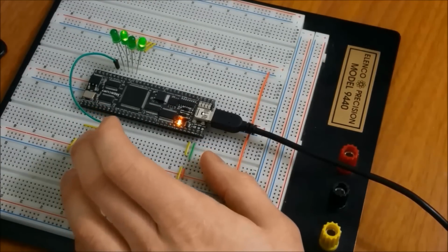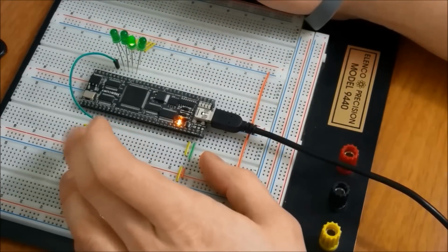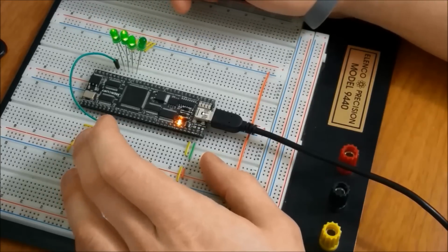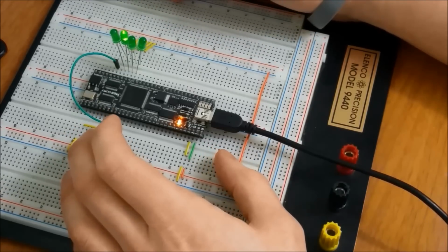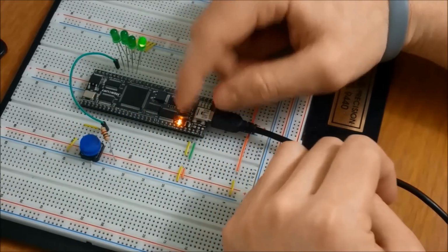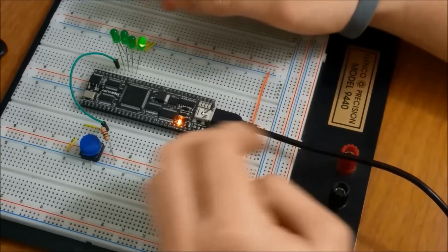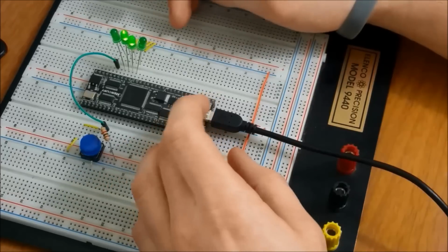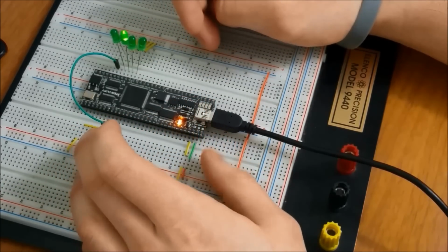If you press the button, you can see it counts in binary on the LEDs, and it will loop back around once you reach hex F. So here it will count back down to 0. And at any count you want, like 4, you can simply reset all the VHDL modules inside of the FPGA just by pushing the button. So from 6, and then set it back down to 1, 2, 3, 4, 5.